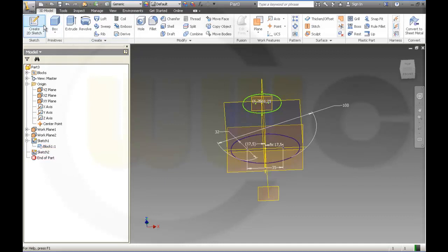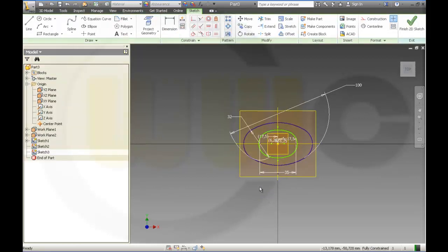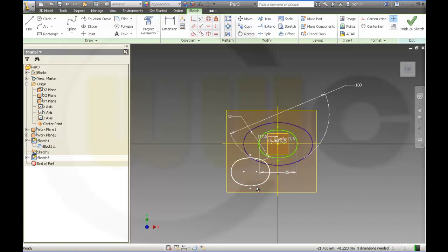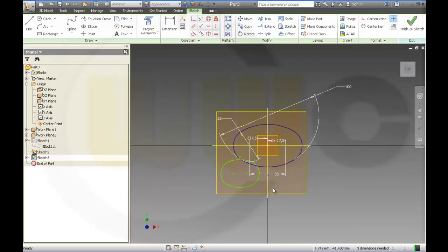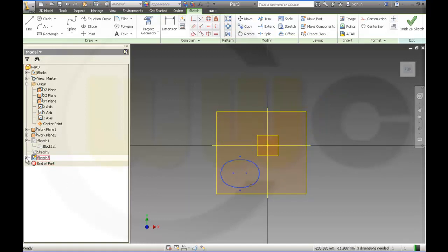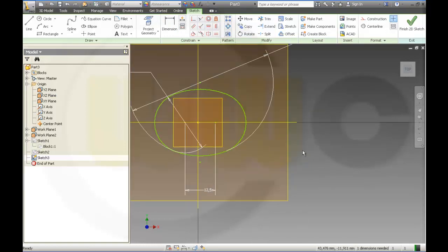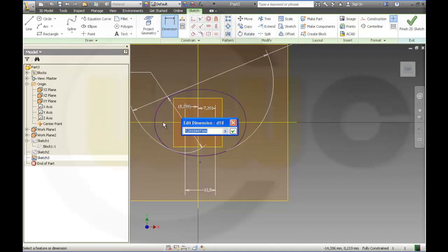then I need another sketch on that plane. Insert again the block. Hide these two sketches. Come on. Okay. And explode the block. Yep. Then align these. Move it over here. Make a dimension. D18. D19. Accept this. And set this equal D19.